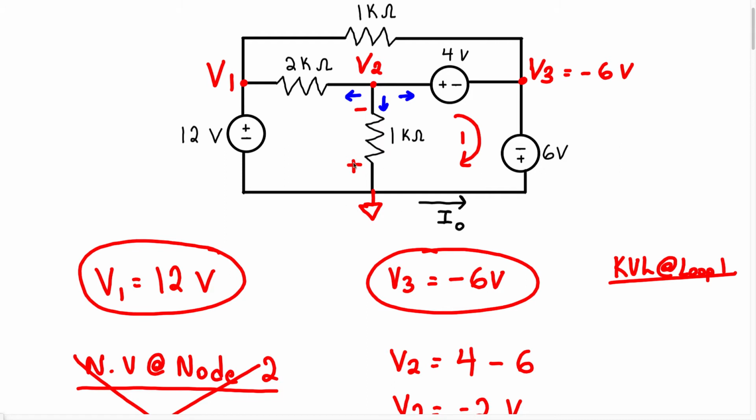So we're going to enter the positive terminal, and because we want to find the voltage, let's just add in a current. So we're going to assume there's a current flowing this way, and we're going to label that current I1, right? So we have I1 flowing into this resistor as we walk around. So that's going to be 1000 I1 for the voltage across this resistor.